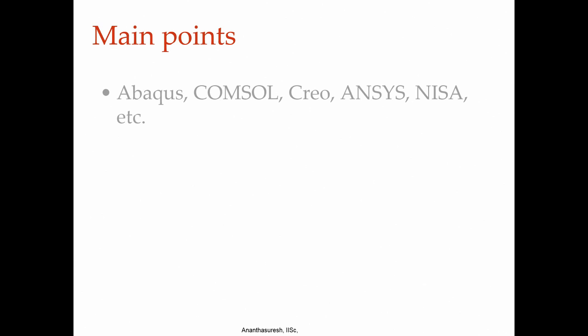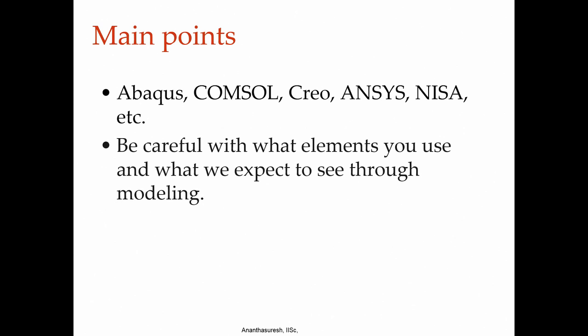So, let us just summarize what we have discussed. We can use any finite element software, it does not matter which one you use, whatever you are comfortable with you can use that. The results that I have shown were done with Abaqus, COMSOL, Creo and some with ANSYS and NISA. So, these are the ones that we use in our group, but just about anything is fine, but we have to pay attention to what kind of elements you use and make sure that you check that option of geometric nonlinearity. If contact is there, you have to define contact elements and do the kinds of things that we saw in two examples today.